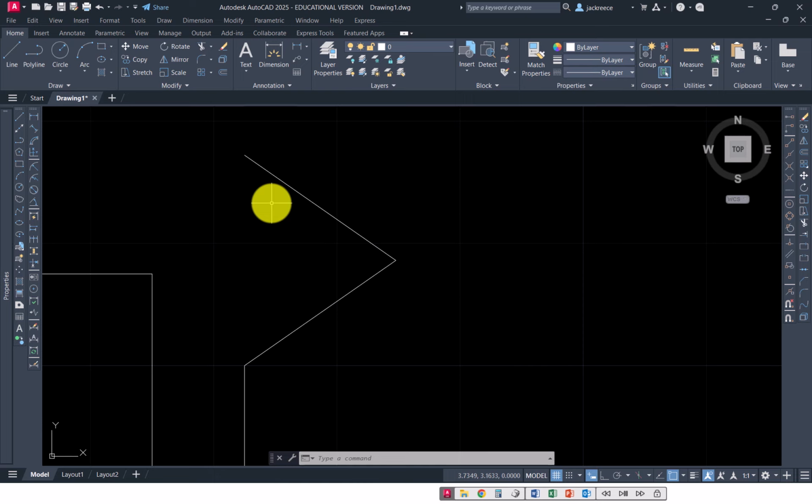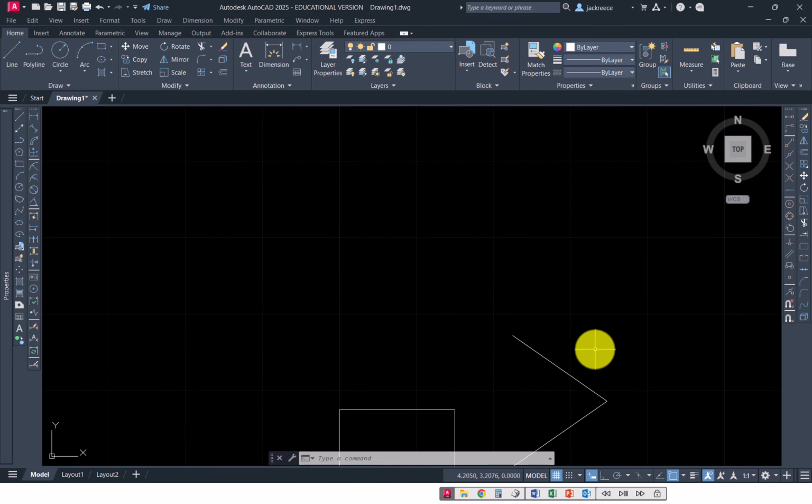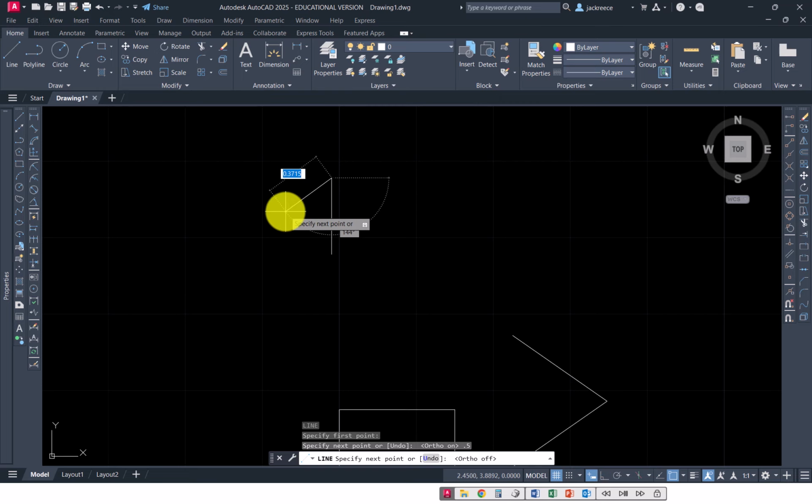Up on the upper left side and on the left side there, you've got some lines where you've got dimensions in an x direction and in a y direction. Here you'll use relative coordinates. Let me start my line command. I'm going to start here, and I'm going to come up 0.5 and turn off ortho mode again. Now it's telling me I want to go 0.625 to the left and down 0.25.